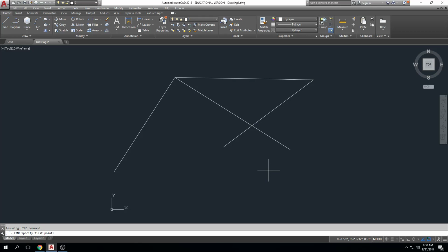You'll see me press F3 so that I don't have them appear and I can look at something. F3, turn it back on, right? F3, instead of squinting and going all the way down to the very bottom corner, finding the icon, clicking on it, you know, anyway. You guys will get used to some of this stuff, right? So F3 only turns off certain... It turns off all of them. Oh, not all of them. Yep, okay, so it's universal. So if I press F3, every object snap shuts down until I press F3 and turn them back on. Yep. Otherwise they're running and they're automatic.